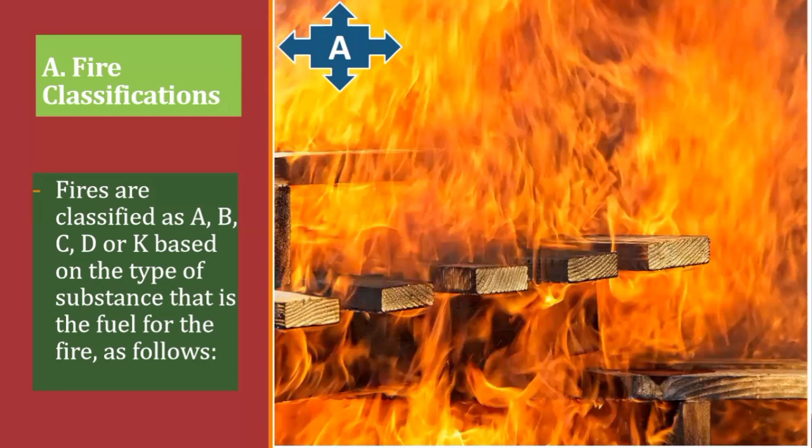Just in case you encounter that scenario, you had better not use water, but use the other extinguisher that can put out the class A fire and also protect the electricity, to avoid the possibility of propagation or conflagration that electricity may cause.